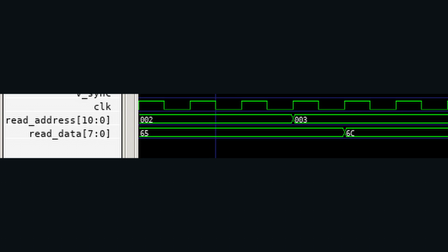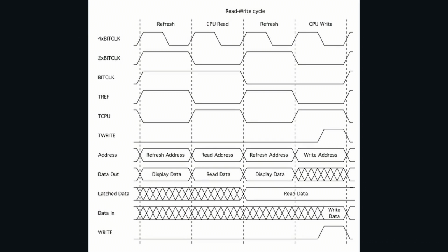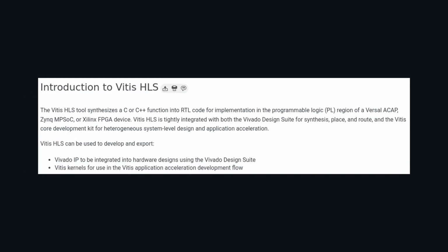Now that value is also delayed by one cycle. You really need to think about this, and I think high-level synthesis just misses this core part of the design. Unless you've already done the work on paper, or in your head, I just don't really believe in it. But professionals disagree, and Xilinx is putting a lot of work into their own high-level synthesis flows, so maybe I'm just a boomer. Basically though, I'm going to use rust-hdl as a Verilog substitute in this video, and I've already done all my designs on paper.